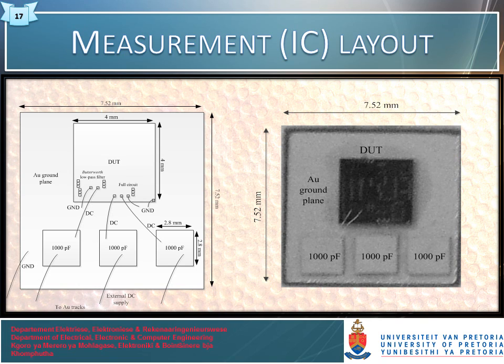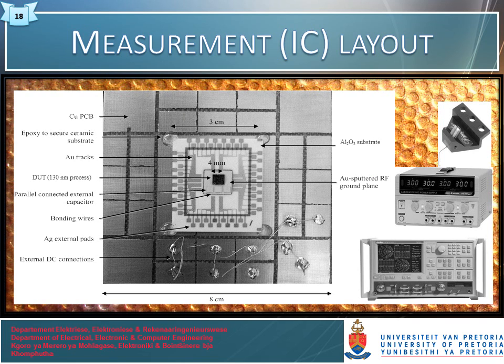The measurement probes were characterized and incorporated within the internal matching networks on the die, and the exclusion of wire bonds on high-frequency connections therefore improved expected measured results through elimination of these estimated wire models. The DUT, ceramic substrate, gold PCB, or printed circuit board, and measurement equipment is shown in this figure. The DUT and decoupling capacitors, as shown in the previous slide, were connected to the external supply through the wire bonds and external wire connections to the ceramic substrate and gold PCB, respectively.